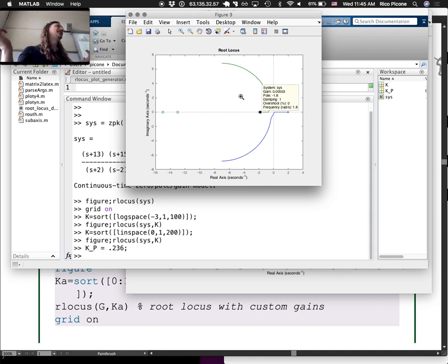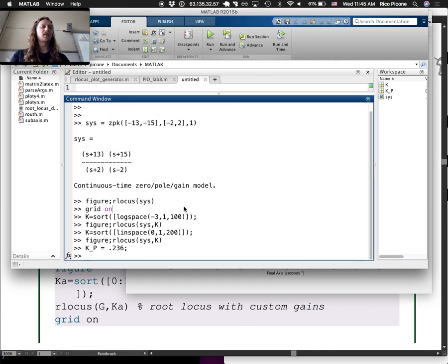Because we don't really have anywhere else to start, so we kind of just always make that approximation, even when it's really bad, which oftentimes could be off by a factor of 2. But otherwise, you're pretty much stuck just guessing and checking. So you start with it anyways, and then you tweak. So let's do it. Let's choose a gain like we did, KP of 0.236.